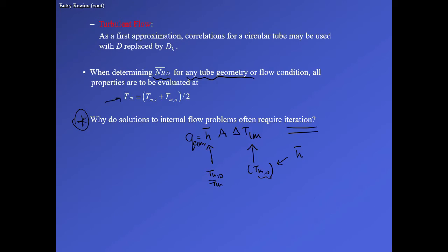So you have to start with some guess for h bar, calculate this, then go back and calculate h bar using these temperatures, and repeat, because the thermophysical properties for the calculation of h bar were calculated using the outlet temperature.